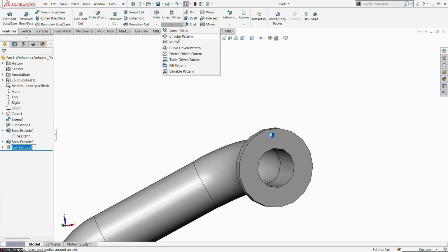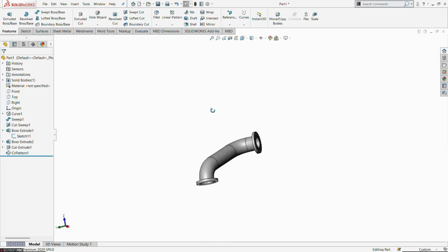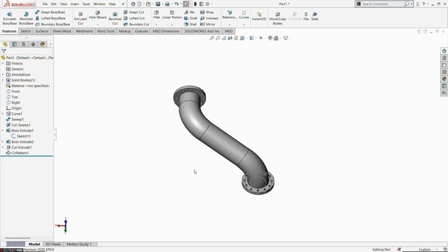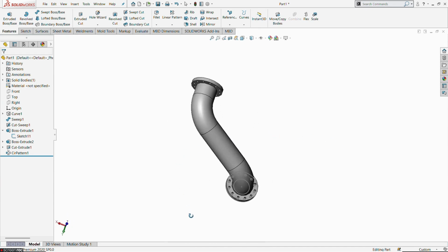Select an extrude cut and choose a circular pattern. It takes the overall pocket faces at the default positions. Then change the instance number to 12. Almost the overall solid body gets created. This is the complete wall design. Thank you.